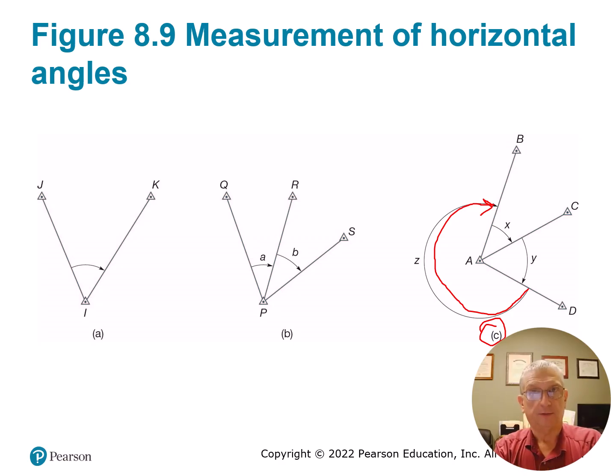You'll be looking at it with an inverted scope that's going to give you 210, and then you swing back around with your plunged scope, and you look at your backside, which is going to be 180. Just say that your backside, instead of being 180, was 179, 59, 54. Well, then that's 6 seconds difference. So you actually turned a 30, 00, 06 your second time, so your average would be 30 degrees, 00 minutes, 3 seconds.